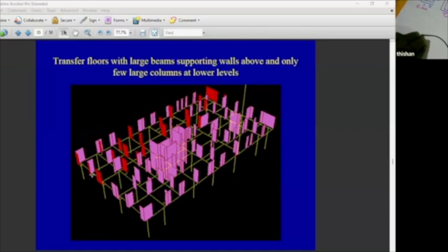Why? It is a fictitious beam, not the actual beam. There's no actual beam like this. It's a beam that we apply. So unless you use zero mass, zero weight, what will happen? All these extra members will add weight and mass to the structure, which is wrong. So anything not there, what shall we do? We'll say the mass is almost close to zero. Weight is almost close to zero when we define the material on the computer program.